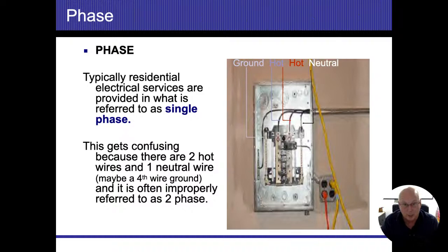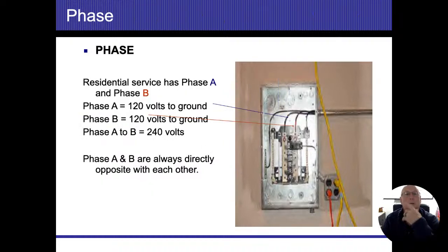They can start creating arc blast that gets really dangerous. It's going to be over all of our heads. I'm going to ask that you refer them off to an electrician and just say you don't know. So don't take the cover panels off unless you know what you're doing on those. Again, you're going to have three energized conductors. The easiest, quickest clue that you're going to see is three breakers all tied together. So typically, again, they're going to be on either commercial buildings or very large residential buildings.